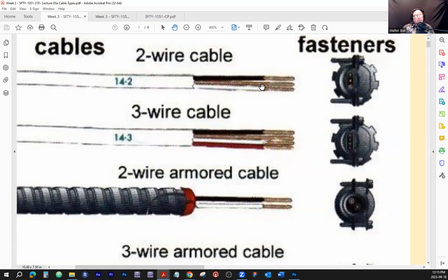And as a review for those of us who already participated in the first lab, what is the difference between grounding and bonding? Electrically, the difference should not matter. However, how it's physically arranged is where the difference is. If a terminal or connector is grounded, that means that from that point there is an uninterrupted wire going straight to a true ground.